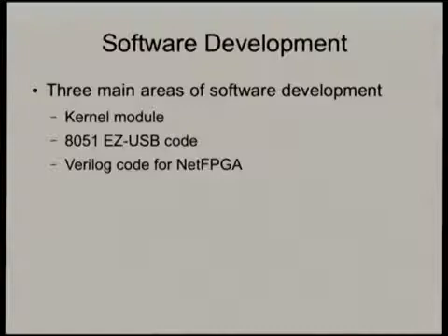Okay, so looking at the software, there's basically three areas that need development. There's the kernel module to drive the USB interface. There's the code that runs on the 8051 microcontroller on the EZ-USB devices. And there's the Verilog code, which is by far the most complicated part of it, for the NetFPGA.